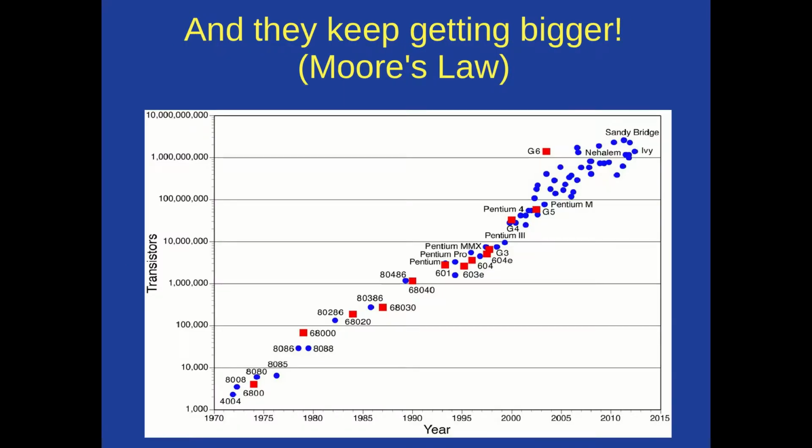So how many people have heard of Moore's Law? So this is Moore as in Gordon Moore, right? And it's really an observation that roughly every 2 years the size of these chips doubles. So way back here in the early 70s, the first microprocessors, a few thousand transistors. 30 years later, year 2000, around 10 million transistors per chip. And 2010, we hit the billion transistor mark.